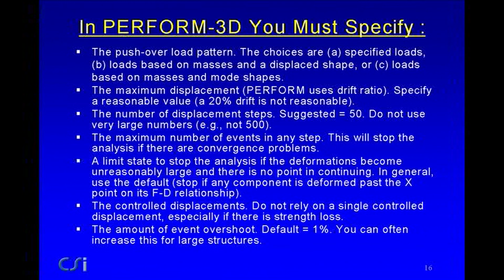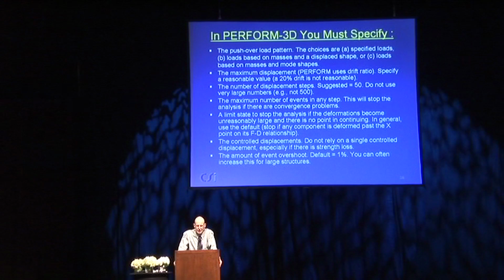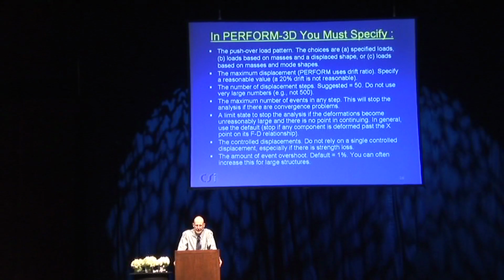So you do have to specify certain things in Perform 3D when you do a static pushover analysis. You don't have to know a lot about the analysis method, but you still have to specify a few things. Firstly, you have to specify the pushover load pattern, and you have a number of choices. You can use a specified load pattern. You can specify a displaced shape, and it will calculate the forces based on that displaced shape and the masses. For example, if you specify a linear displaced shape over the height of the building, this would correspond to a triangular load pattern, but based on the masses.